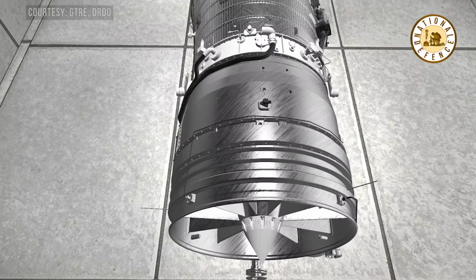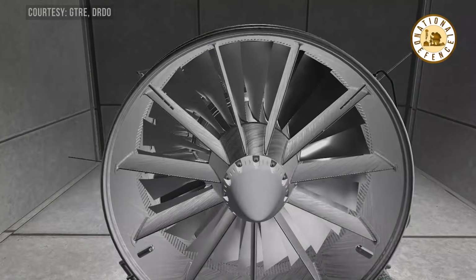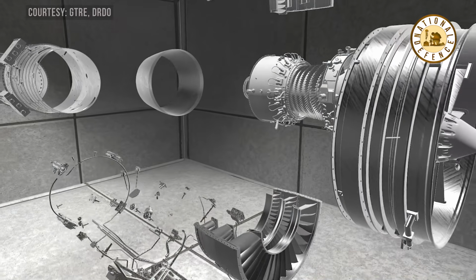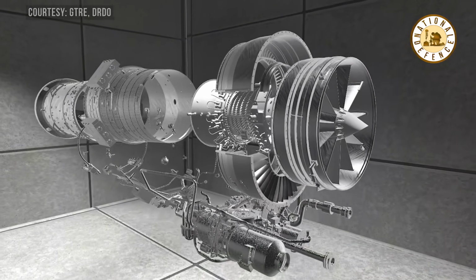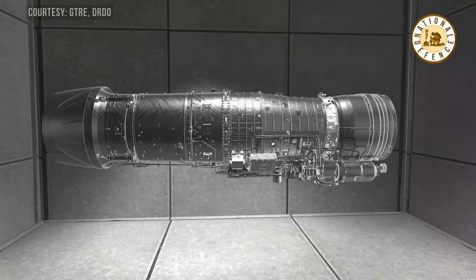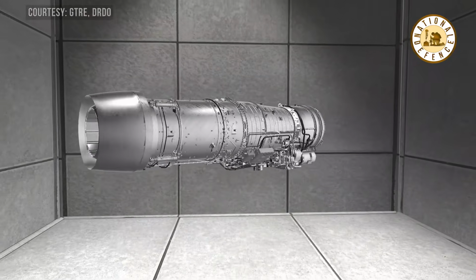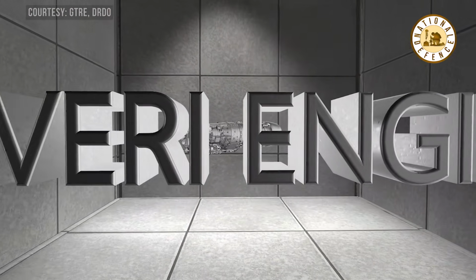And for the turbine side, we have a boltless blade retaining arrangement. There won't be any bolts. In a simplified way, if you want to tell, you know the cooker, everybody knows. One piece. Yeah, now you know the cooker. There won't be any bolts. You insert it, circumferentially lock it, it cannot come out, whatever the pressure. I am telling it in a very simplified way, but we are going ahead with a boltless blade retaining arrangement so that a lot of weight can be saved.